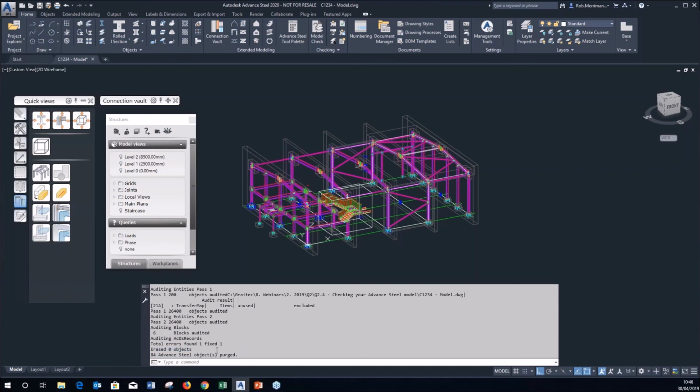It will also show you if you've got any duplicate holes on top of each other, and it will try to delete those duplicate holes. If you've copied something and you've got holes on top of each other, it will say you've got 2 holes exactly the same size in exactly the same place, and if it can, it will delete one of the sets of holes.